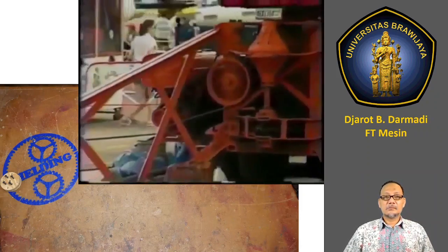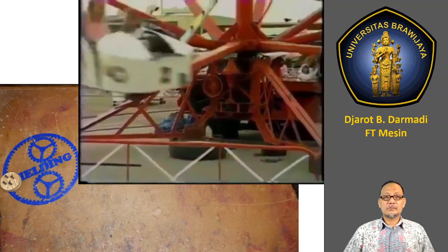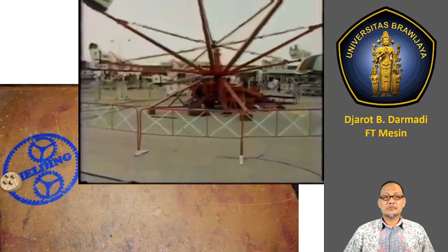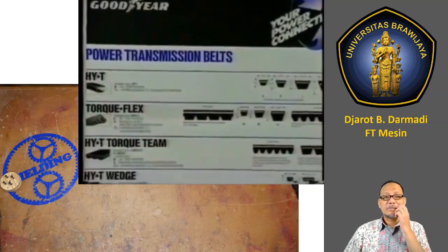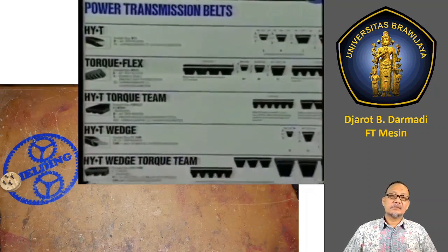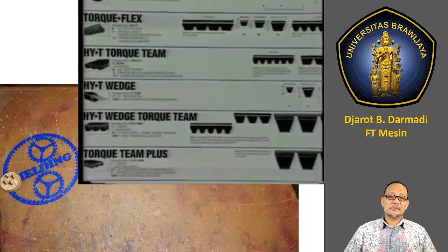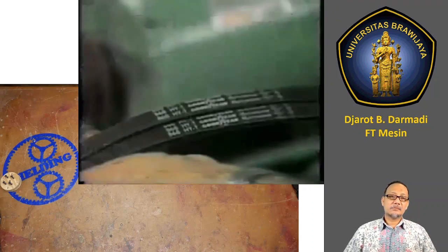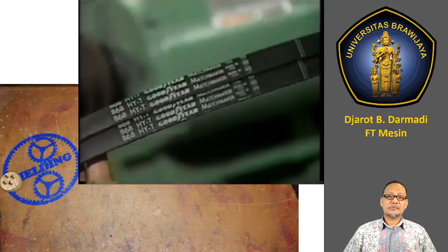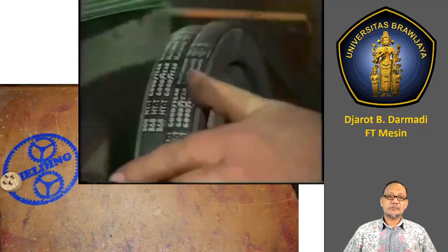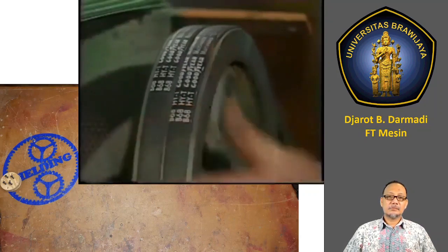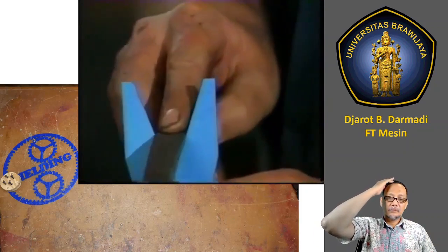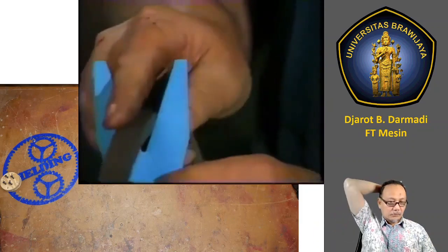The increasing demand for higher productivity has resulted in a wide variety of V-belt designs capable of handling specific applications. Each V-belt type has a specific design for a specific function, and the identification nomenclature is different for each belt. The differing ID numbers make identification and selection simple. This allows for quick replacement and minimal downtime. If the ID numbers have been worn away, the belt size can be checked by using a V-template gauge.